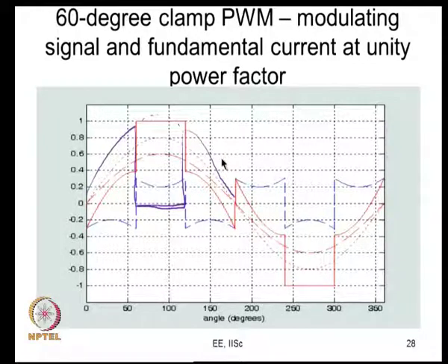So, you can use the same E on and E off, and here the energy loss is 0 because there is no switching, and you can calculate the average E on and E off, and you can multiply that by the number of switching cycles that it has effectively had, and you can find out how exactly the switching loss can be calculated, because the energy loss is known to you. This is how energy loss is, and then you also know the switching frequency, how it is going to change here, except that you have got to account for this particular factor.